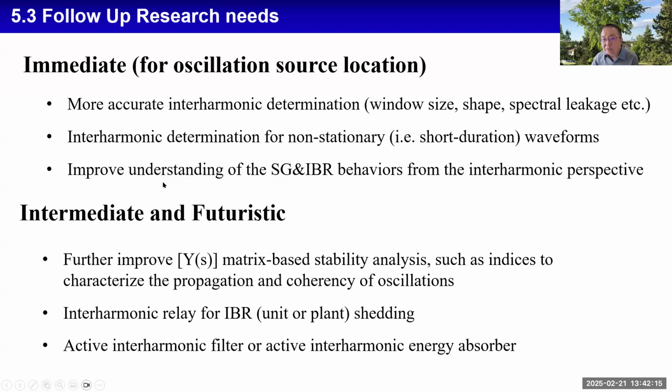And for me, I really want to understand the SG and the IBR behavior, and especially the phasor behavior from the interharmonic perspective. Immediate future research needs include using matrix-based stability analysis, such as characterizing the propagation and coherency of oscillation, and using the participation factors. Now, interharmonic relay, maybe for load shedding, for generation shedding. Can we use an active interharmonic filter or active interharmonic energy observer to damp power system oscillation?